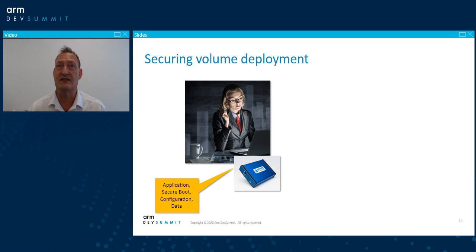A secure boot manager. This is a very critical part of protecting products today, outside the scope of this talk, but I'm sure most of you are familiar with the need for a secure boot on a product to protect secrets and applications. We may have some configuration data that needs to go in there for the particular product, and other forms of data such as databases that are referred to, perhaps a list of servers that need to go into the end product. So the production planner here will pull together all that information and will save it securely inside the HSM.